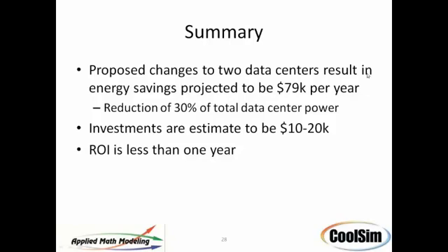All right. What kind of sensors are used to collect the data to determine where to place the air curtains? We don't use sensors to collect data to know where to put the air curtains. We just simply look at the flow patterns generated by the CFD, and you can tell where to put them. It's not very difficult. The air's leaking around the back. You look and see where it's leaking from the returns and getting drawn back into the inlets.